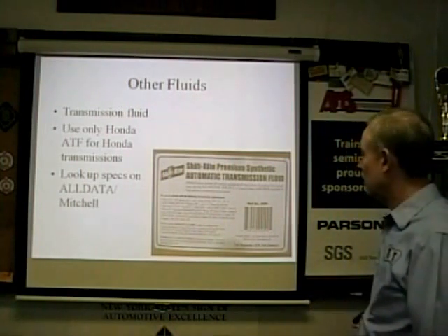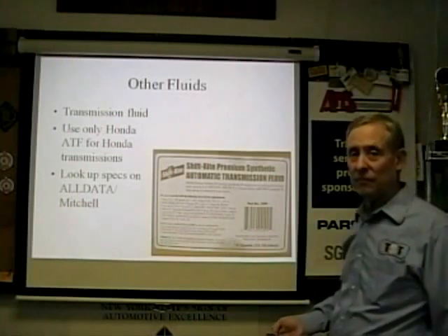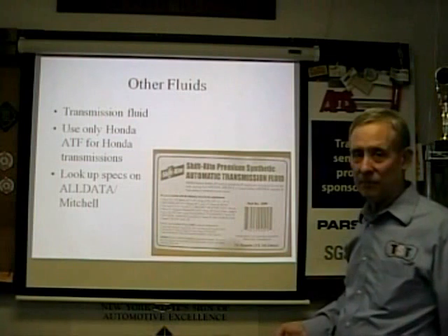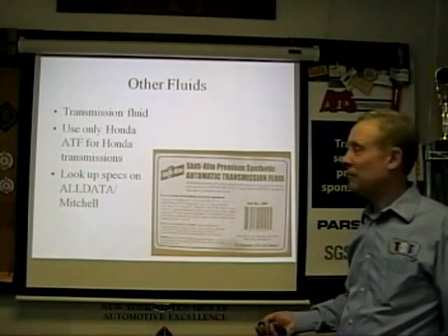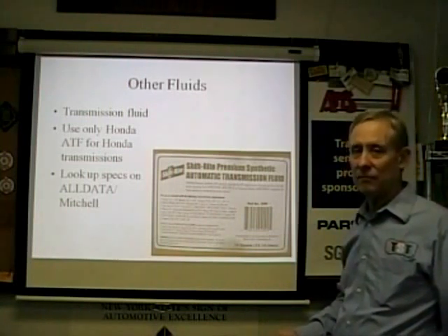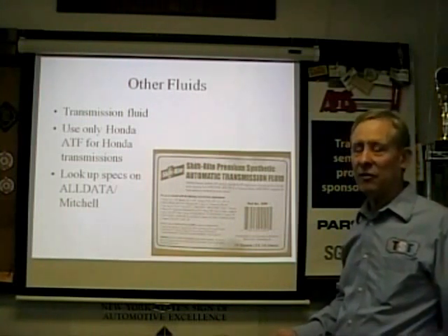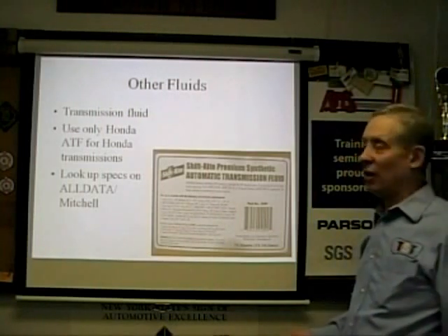Just a note on that Honda: guys that rebuild trannies, some of our members, Mike and Pete and Kevin, will tell you that Hondas are real finicky. Even though LubeGuard's a great product, you have to be real careful. You're probably better off using a Honda fluid, or that synthetic they have there, which seems to work okay with the modifier.